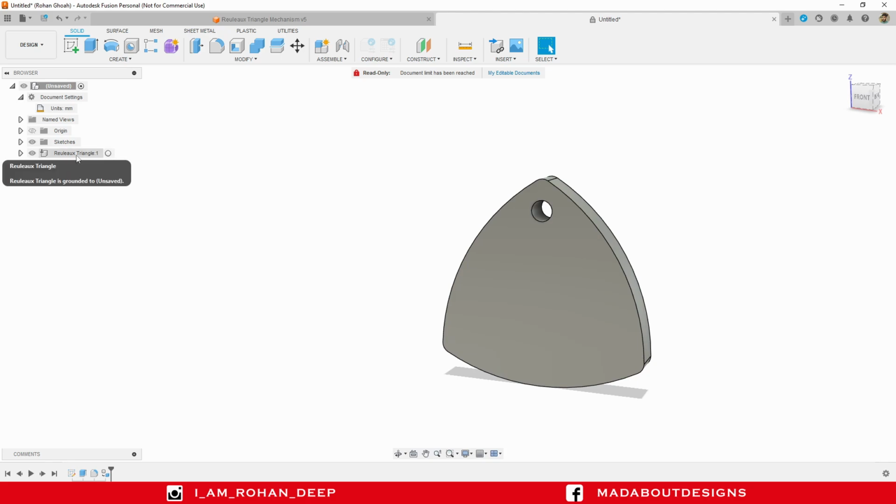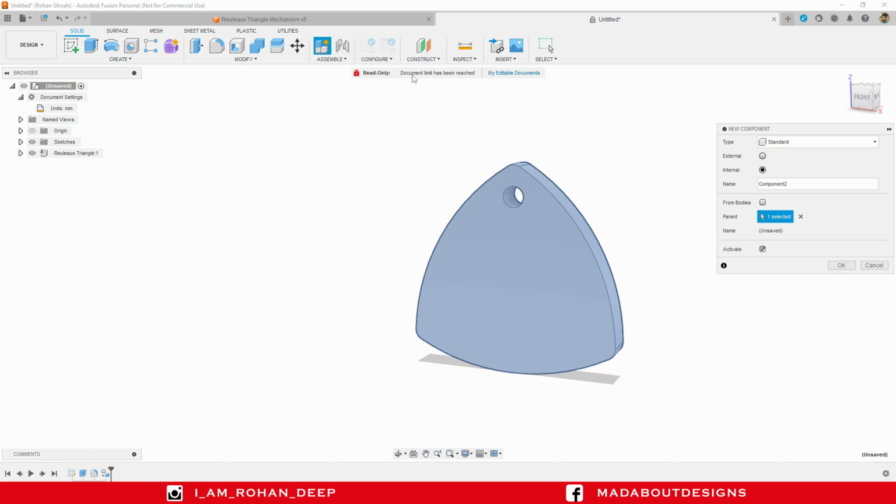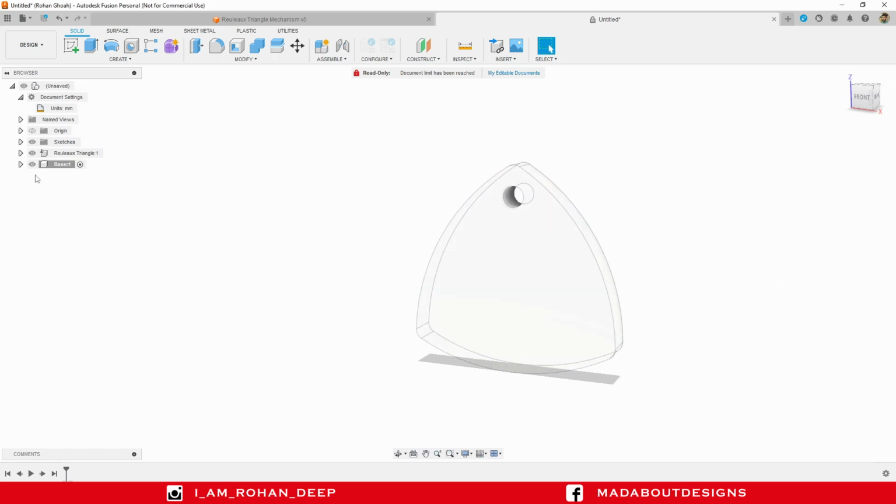You can see this component is under our main component assembly. Now let's create another component and give it a name, base. It will be an internal component of our main assembly. Parent, this one. Activate, click OK. Here is the base. So we need to create the base under this component.